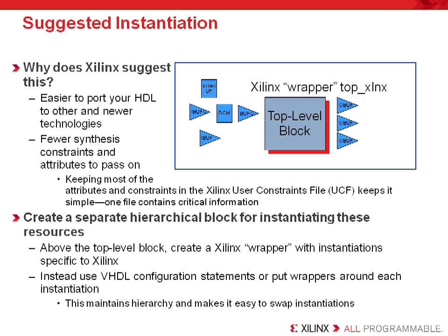Another instantiation option a designer has is to use the VHDL configuration statements or put wrappers around each instantiation. Now this will maintain the design hierarchy and still make it easy to swap instantiations if your design migrates to another architecture.